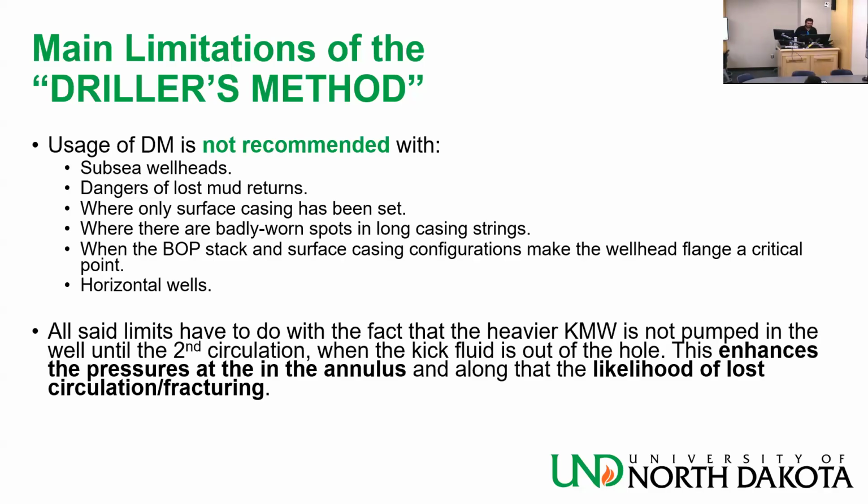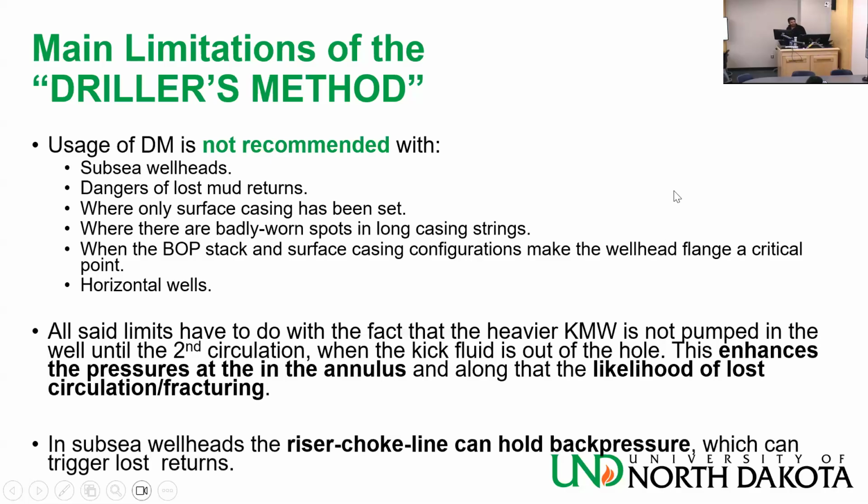Anyway. Are they waiting? Oh, okay. In subsea wellheads, the riser choke line can hold back pressure, which can also trigger lost returns. That means you can have pressure on the choke side, additional SICP pressure, and then that can make your situation even worse. You need to be very careful with this stuff.